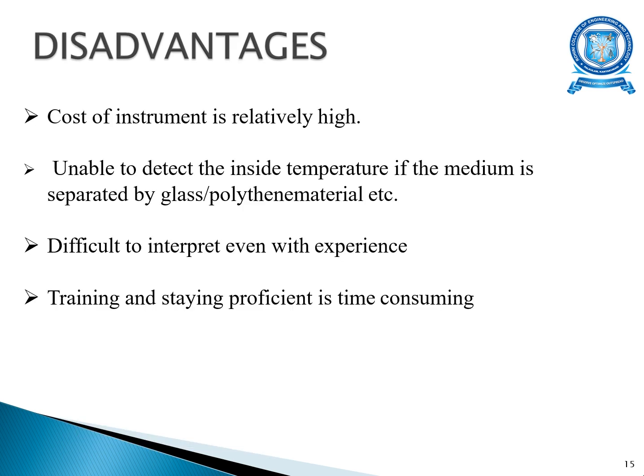The disadvantages of thermography: the cost of the instrument is very high. It is unable to detect the inside temperature if the medium is separated or is a poly material, etc. It is very difficult, even for an experienced person, to interpret the result, and training and staying proficient is time consuming.